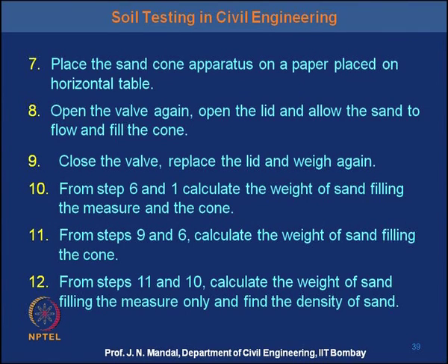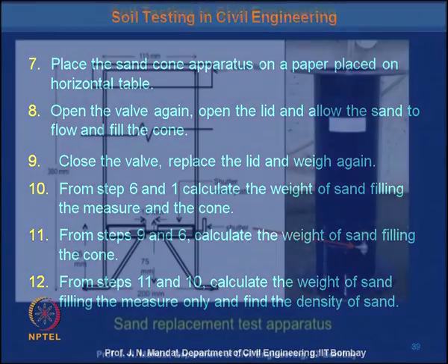From steps 9 and 6, you calculate the weight of the sand filling the cone. From steps 11 and 10, calculate the weight of the sand filling the measure only and find the density of the sand. So, this is the process for the determination of the density of the sand.